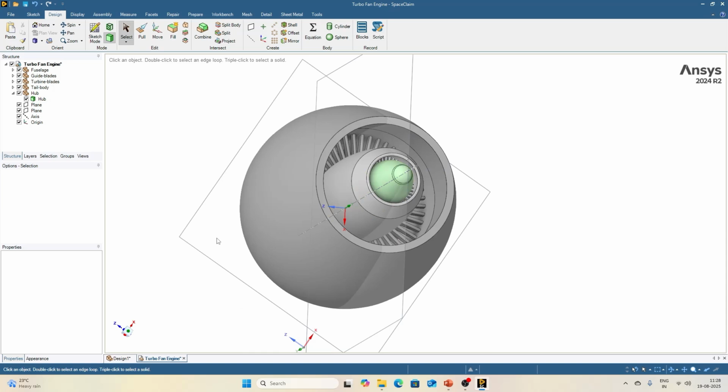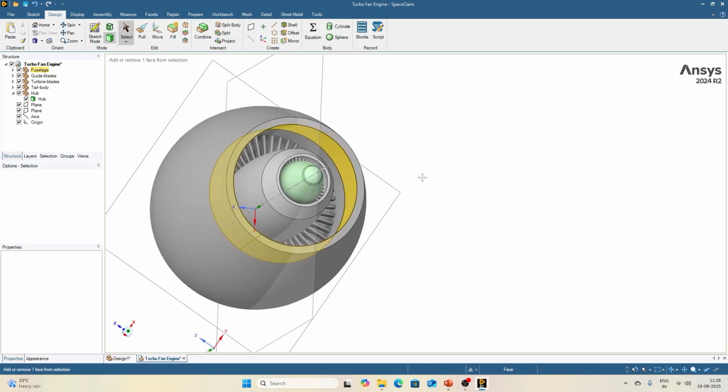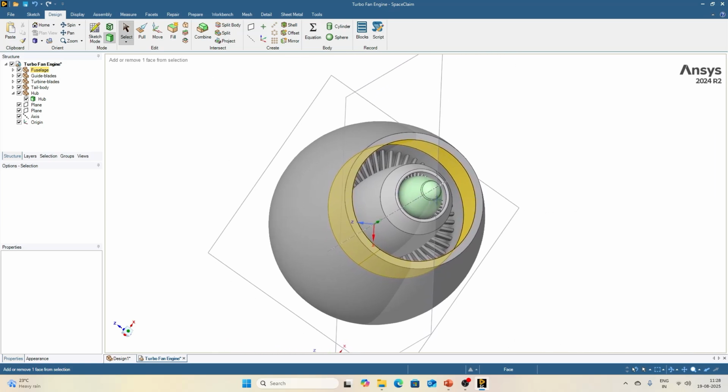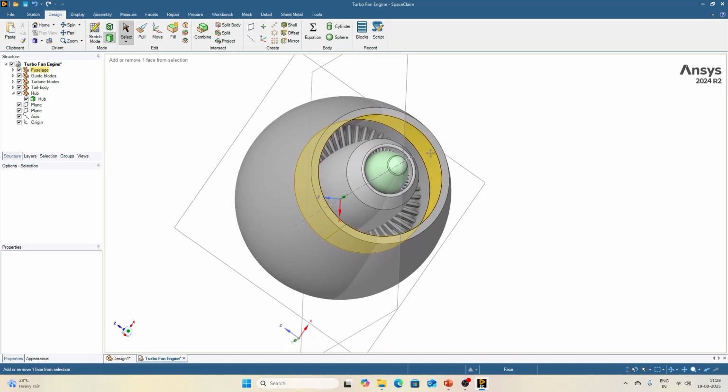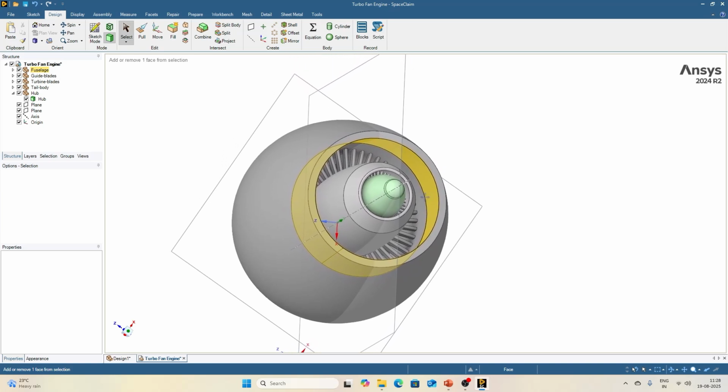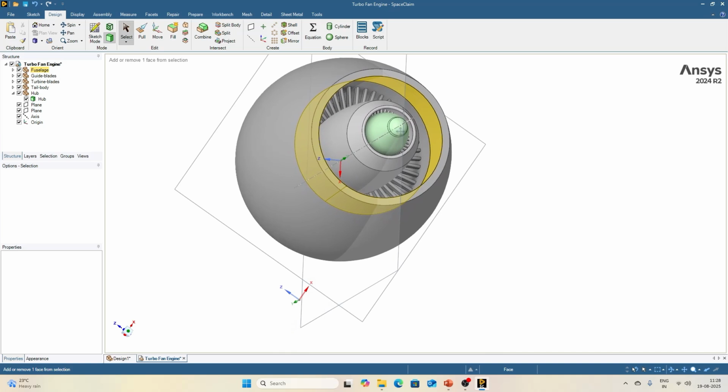If you want to pan the model, or move it vertically or horizontally in a plane, then you can use Control and the middle mouse button. Press Control and click the middle mouse button or roller to pan the model around the display. Please remember that both should be pressed all the time as long as you want to pan the model.